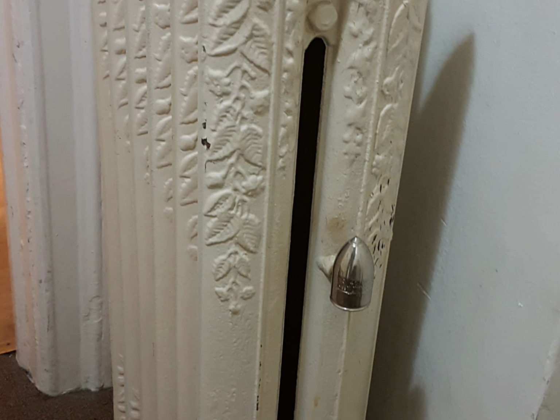The boiler could still build up pressure as they were heating up, and the vents would not close, or wouldn't close completely, until the radiators heated up. And when he talks about the drop away pressure, this is just what I've observed in my heating system when I used to live in this apartment back in the day. The boiler that I had in my apartment, I set to cut out between 7.5 and 8 psi.